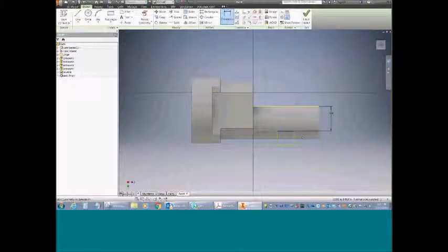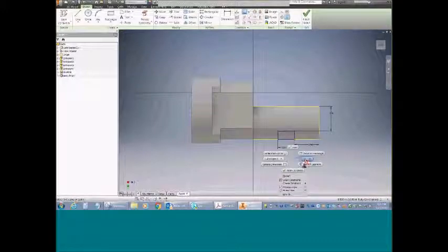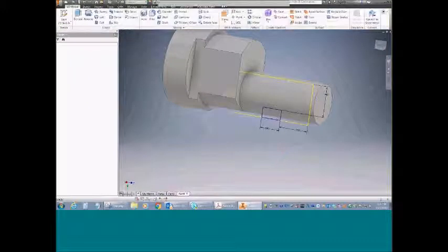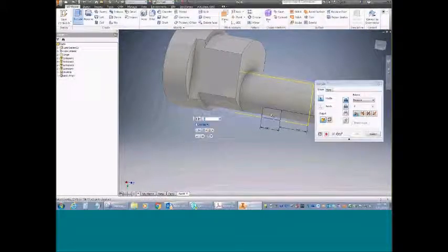It should be 0.75, distance from the edge here, need 0.75 there, and then I have a width, and that is 1/2 inch. And I probably should project the bottom edge of this cylinder, and then use my coincident constraint and put that point coincident to that, so my rectangle is the appropriate size. Finish that, and extrude that rectangle to cut.